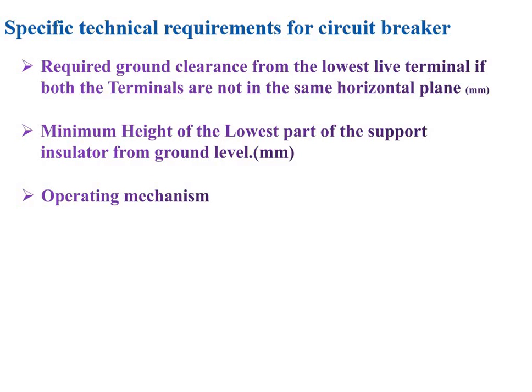Then next is the auto reclosing duty. Once there is a fault in the system, the main function of the circuit breaker is to isolate the faulty section from the healthy section. So if a fault is there and that fault is temporary, still the circuit breaker is going to trip.